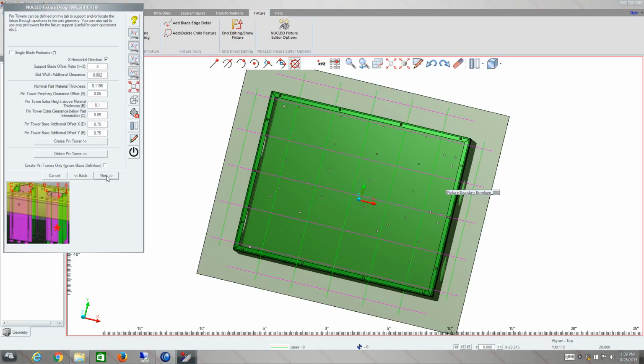This option is a pin tower option, where you would have maybe traditionally put a machine pin in a fixture, so you could locate through a feature in the weldment. This does the same thing. What you do is you choose a circle or a square, whatever shape you like, and you pick the edges of the square, and it will then project a tower underneath that position, so you can locate through that feature in the weldment model. There's two types, one for a bigger hole, one for a smaller hole. So you can choose which one suits you for the particular feature you're trying to fit through.